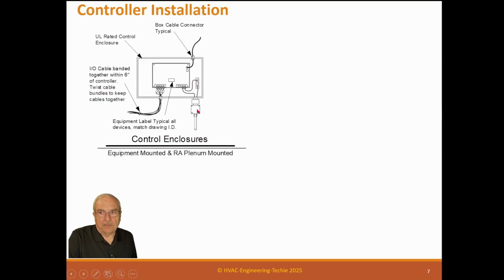So you brought the conduit of power into this J box, wired the transformer up, and inside the can, we're not mixing voltages again. So also on our cable, when we have free air cable coming out of a panel, we need to secure those cables somewhat close to the panel. It's all done to try to prevent mechanical damage, someone running into the wire or something like that. So we don't want to do that.